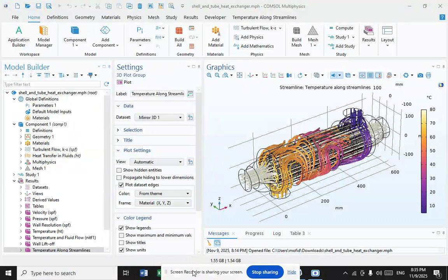They can also prevent the tubes from vibrating. The most common type of baffle is the segmental baffle. The semicircular segmental baffles are oriented at 180 degrees to the adjacent baffles, forcing the fluid to flow upward and downwards between the tube bundle.